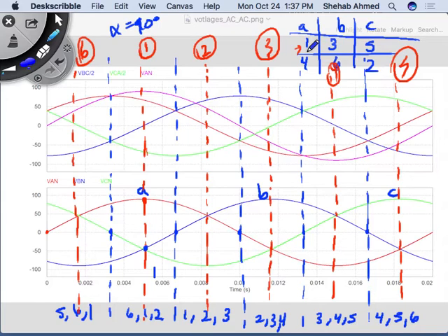It will go from the higher voltage to the lower voltage, right? So now I have a higher voltage at phase A, and then I provided a firing signal for thyristor 6 here, right? For thyristor 5 here. 5 is what? 5 is the top device on phase C.